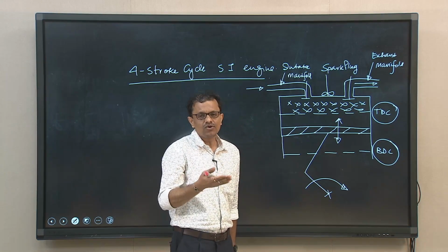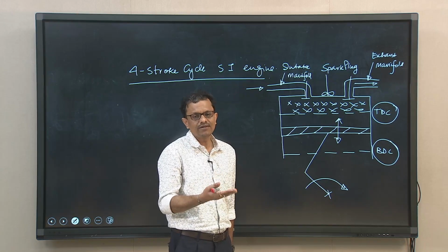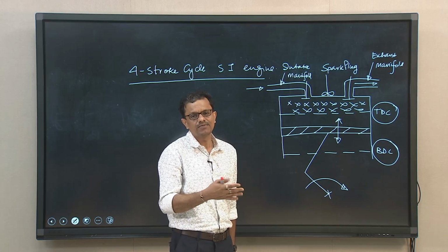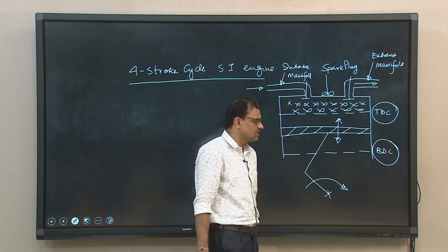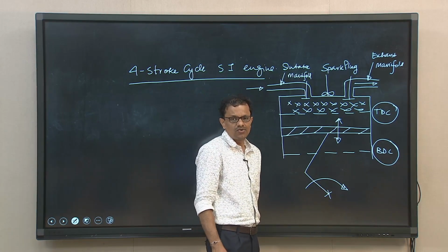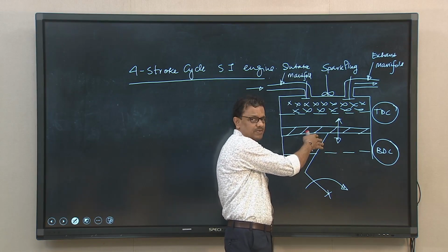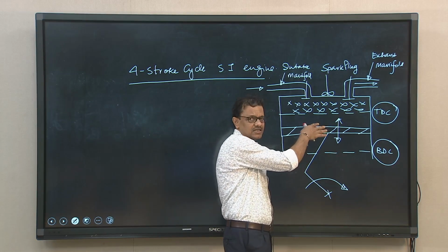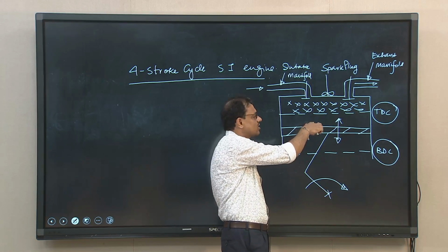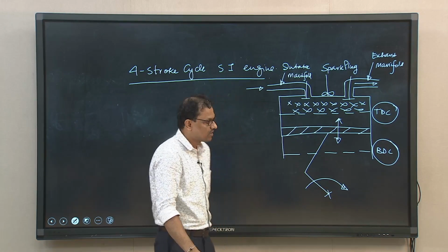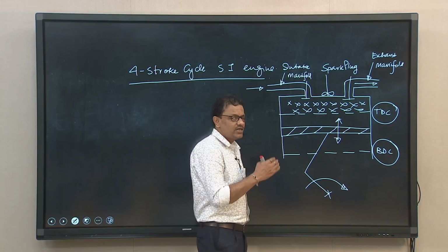So, we need to know what fraction of energy is recovered, and to know that we need to quantify the thermal efficiency or mechanical efficiency of the engines. Forget about mechanical efficiency because you have studied all these things in your undergraduate course, but now we can analyze the cycle and we can also calculate the thermal efficiency, that is the indicated thermal efficiency, that is the energy which will be available inside or at the top of the piston face. Okay. So, now to analyze this we need to